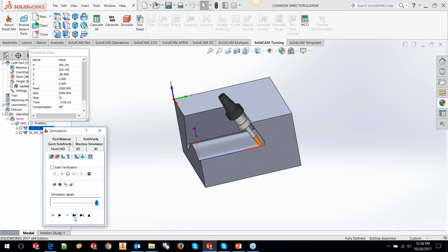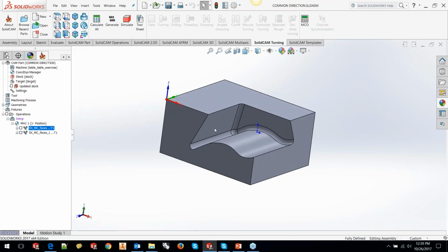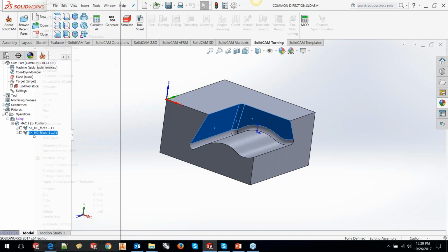Okay. Now, what does common direction do? Common direction takes into account the check surfaces that you have defined. Okay. And then it tries to find one 3+2 position, a perfect 3+2 position, which when applied will remove all the 5-axis motions. It will just tilt the tool to that particular A and B, B and C, or A and C angle, lock itself, and do every machining in 3-axis. Okay, so what you have in common direction here.